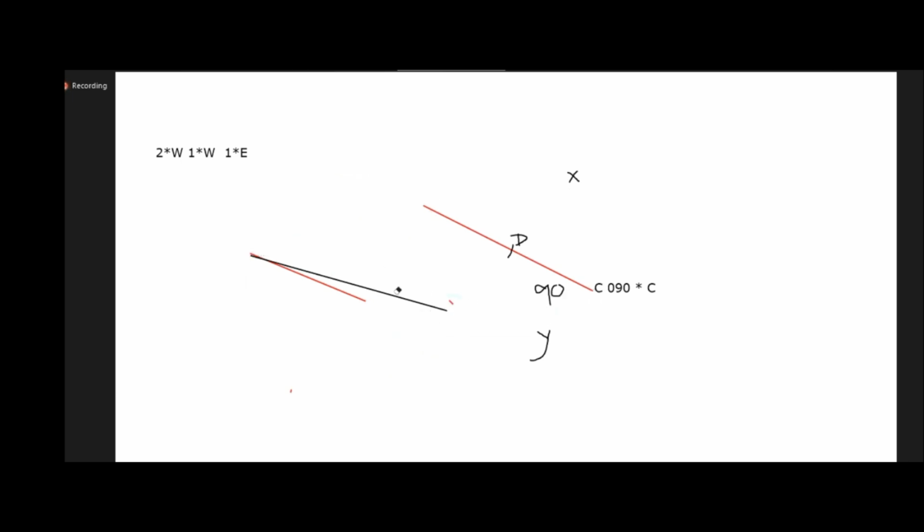Okay, sir. Now, if you get a 180 degree angle, we don't get a position, we get a position line. Suppose you get the A bearing is your 250 degree compass, and the B bearing is your 070 degree compass. So they are in opposite direction.